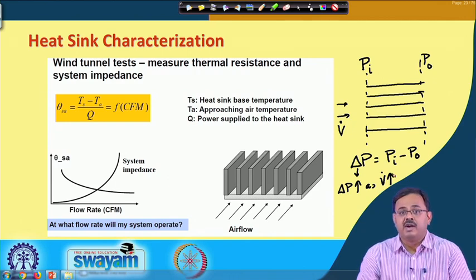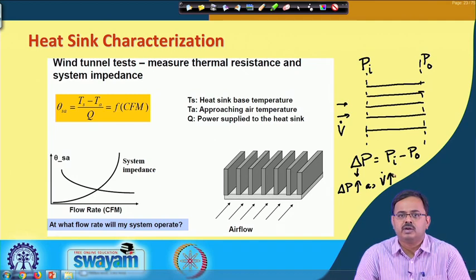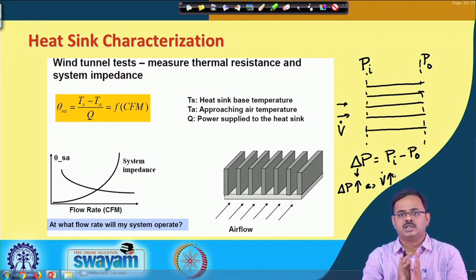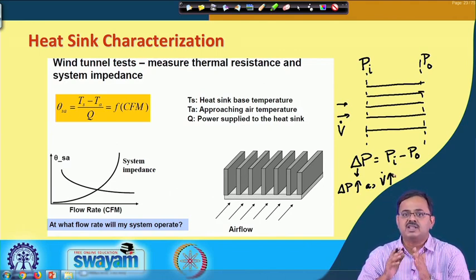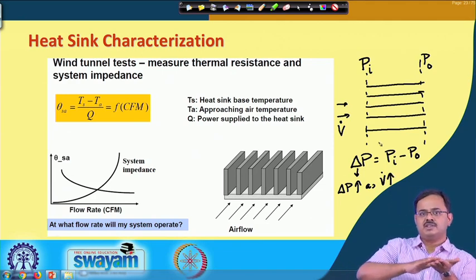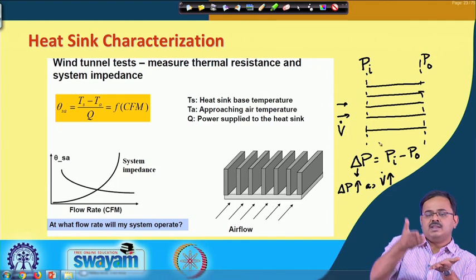Okay. Now, why does this pressure drop happen? That goes a little bit into the details, into the flow physics. This is because of frictional resistance at the walls. Because it is a viscous fluid, whenever a viscous fluid flows over a surface, it is called a no-slip boundary condition, especially at macro scale, where the velocity is 0 at the wall and then it goes up.